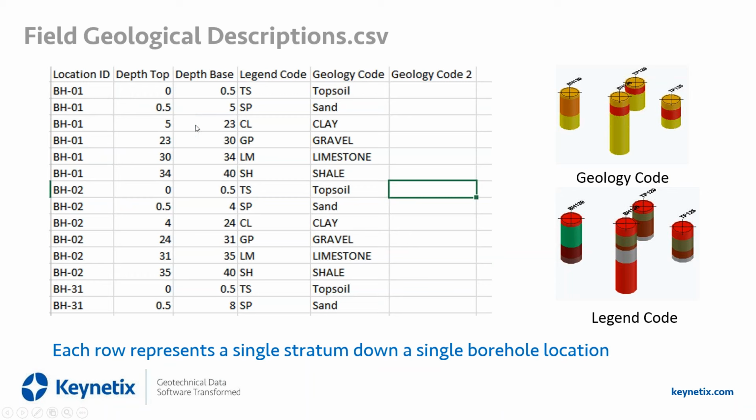So as you can see, as we go down, we have the soil classification together with a lithology name we're calling it. The point where we have 2 or 3, you don't have to have them, is that inside the geotechnical module, you can choose which one you want to band and display. So it gives you more flexibility with the software.